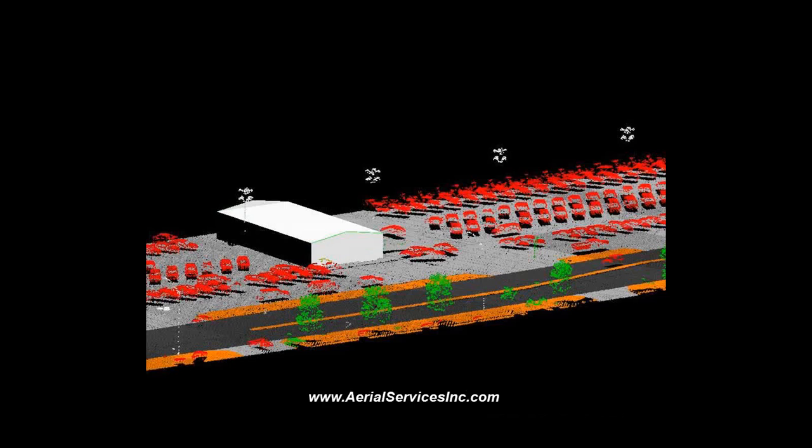Some of what we have is proprietary, some of it's off the shelf. As far as producing things from LiDAR, I said we use MicroStation, either TerraScan or TerraModel, or one of their suites of products. To output product, we can do outputs into typical GIS or CAD related. So if someone wants to know, say they want to move dirt, and they know they've got to move 100 truckloads, and they know that it's $1,000 a truckload, they get to the end of the project and find out that the way they were doing it, it's really 200 truckloads.